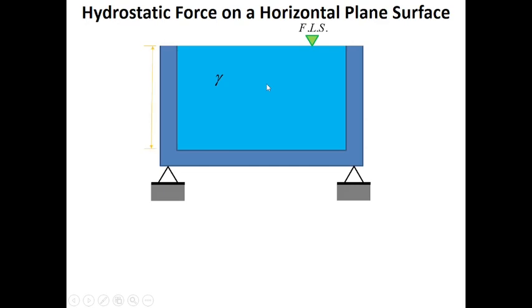And we have here the height of the liquid, or what we call the pressure head. Okay? It is the pressure head because this is a free liquid surface. So at a free liquid surface, the pressure with respect to the atmosphere is zero gauge pressure. The gauge pressure is zero at the free liquid surface.